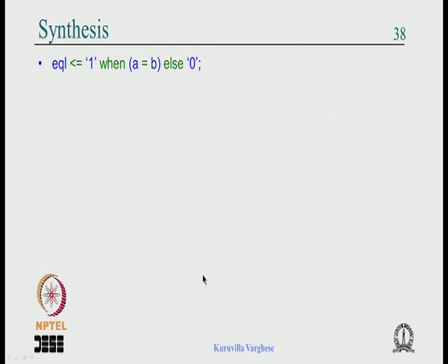A lot of computation: if an event happens at 100 nanoseconds, the simulator may have to compute some 10 processes and 15 concurrent statements, depending on the complexity of the description or the circuit. That should be kept in mind.